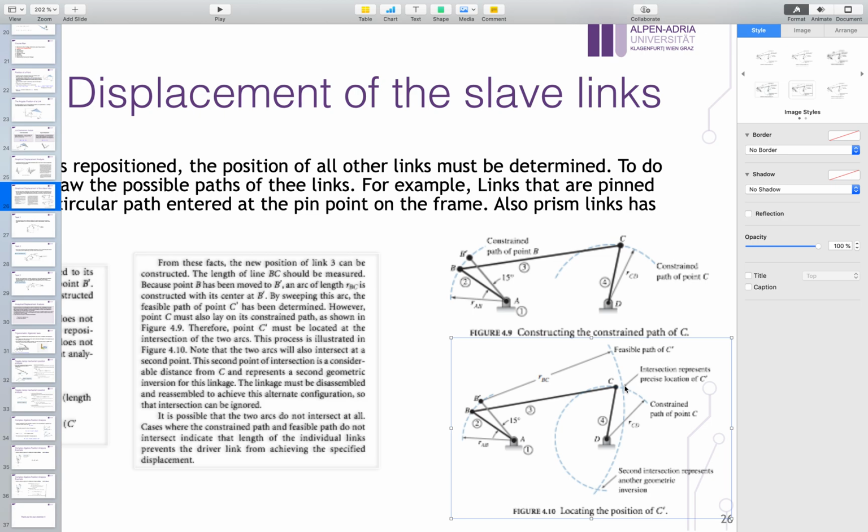They have the same angular, no, sorry, they don't have the same angular displacement because they are on different links. You remember that? If they are on the same link, they have the same angular displacement. If they are not on the same link, then they don't. Now, B and C, actually they are on the same link, because they are two points on the same link. So they would have the same angular displacement, but they don't have the same linear displacement.